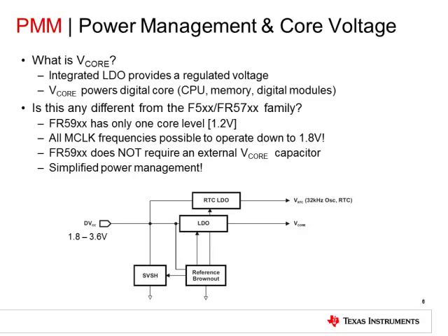The PMM uses an integrated low dropout voltage regulator to supply the core voltage while being powered from DVCC. The core voltage supplies the CPU, memories, both flash and RAM, and digital modules, while the DVCC supplies the IOs and all analog modules, including the oscillators.